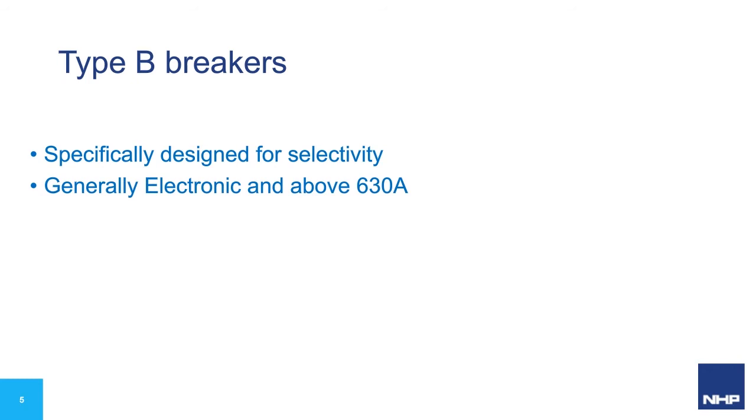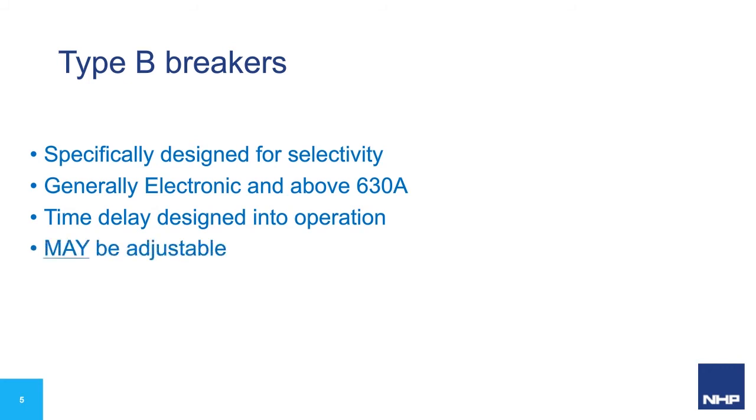There are a number of riders on the behaviours and expectations of ratings along with the previous explanations. However, in a nutshell, the description is a fair indication of the behaviour of electronic OCR MCCBs, and while still highly current limiting in their operations, are frequently referred to and classified under the banner of Type B. This is because the command to unlatch the contact set is often delayed slightly due to processor speed and/or programmed intentional delays.